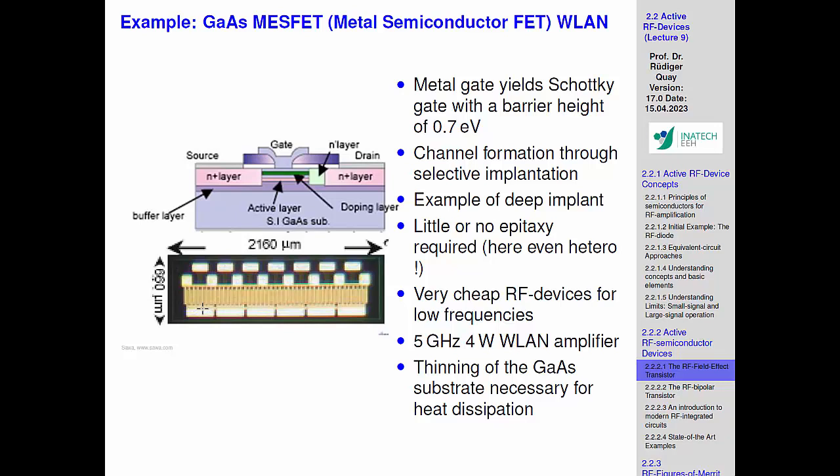But it's really a challenge, because if the wavelength also reduces, you are geometrically not able to keep that in phase. So when we go to higher frequency, smaller wavelength, the transistors also shrink. Yeah? Which directly means you don't have so much area, and area is power because area is current. So that's why we have higher losses at higher frequencies. And at the same time, we have to make the devices smaller. This is a double contradiction. You have harder opposition and you have less forces to counter them. So both things are working against us.